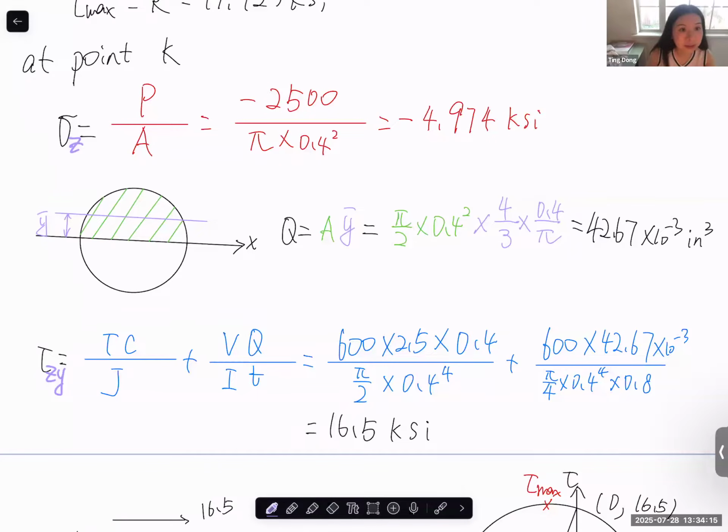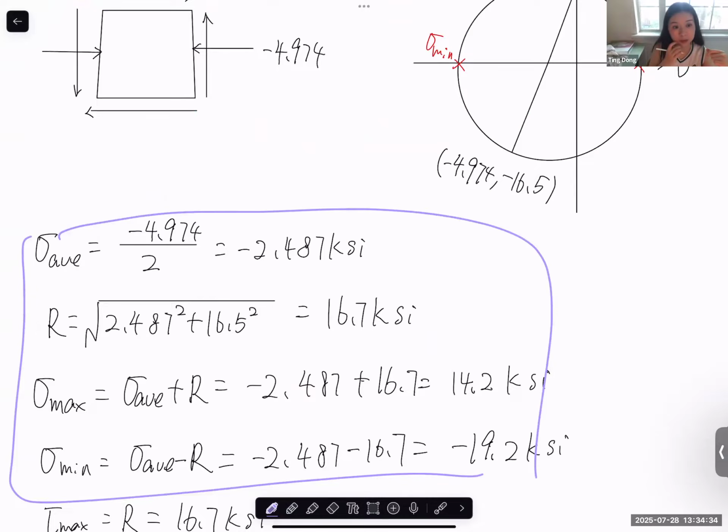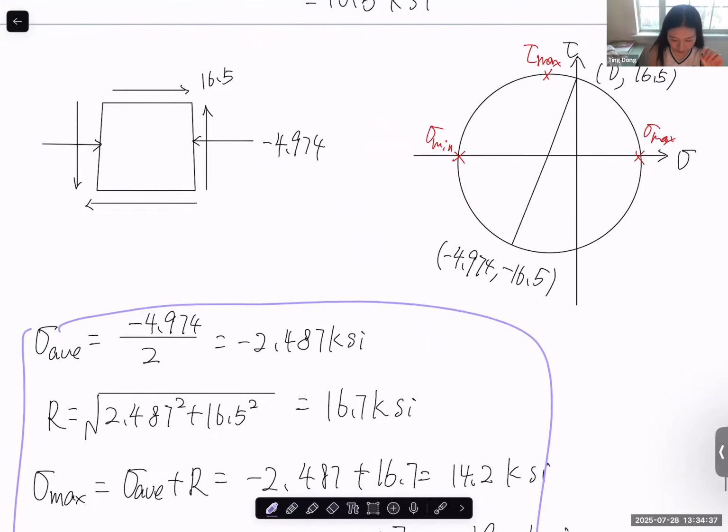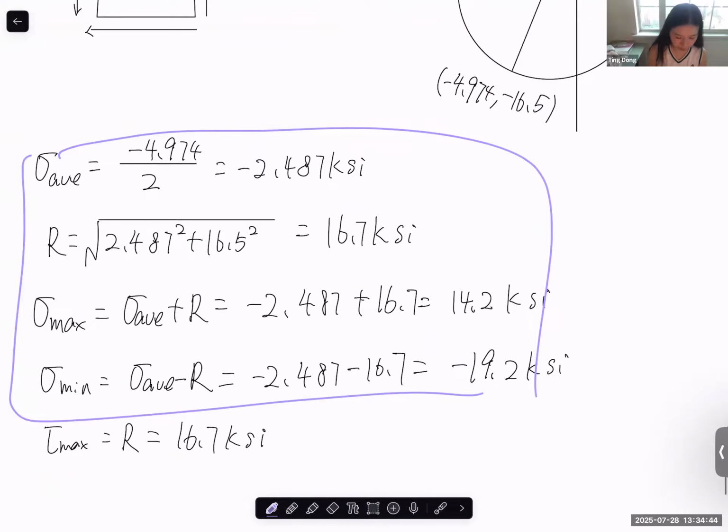Again, yes, it's a 3D problem, but we only have everything in the z and y axis. So it becomes a 2D problem in our calculation for principal stresses and maximum shear stress. I will update this part after class. Because this method uses Mohr's circle, but we didn't have time to cover Mohr's circle this semester. But it's the same. I can use the equation method to calculate maximum shear stress, maximum principal stress, and minimum principal stress. It's the same thing.